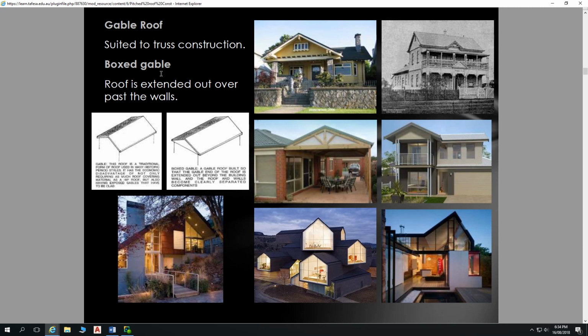Those gable ends can be like a standard gable end, or it can be a boxed gable end, as in this scenario, whereby this gable end is filled in. So we need to do that with outriggers on the roof, and then outriggers from the wall frame, and fill in that gable. So that roof style probably have a truss frame in there.